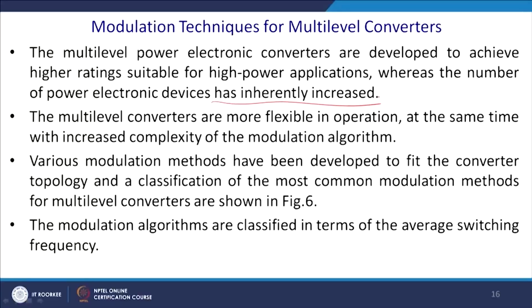That is one of the disadvantages, but the power rating of these devices is lower. The multi-level converters are more flexible in operation because you can have redundancy in the switching states. At the same time, with increased complexity, the modulation algorithm is required to be more complex.